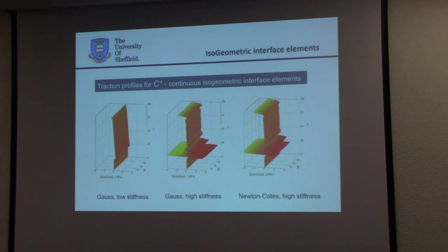At some point, I also did a calculation with a shell element, a thin shell element, where you get wrinkling. In this case, the standard finite elements converged much faster than when we had an interpolation using NURBS. And the reason is, when you have wrinkling, when you have the possibility to have a bit of kinking at the C0 continuity line between elements, that helps you. I mean, it's not the good way, in fact, you make an error to fix an error, but it helps you. Well, if you do it totally properly, using the right continuity with NURBS, it converges slower. So, it doesn't always help.